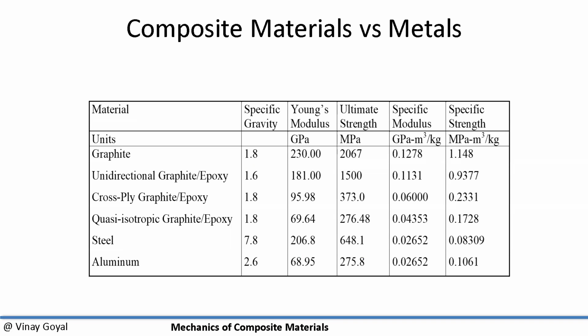For example, in a pressure vessel design, a 0 plus minus 45 90 may not make sense because I have a lot of hoop stress, so maybe hoop plies make sense, 90 degrees alone. And then I have a significant axial load, which is basically half of the hoop. And so I want to also consider that in the assessment.